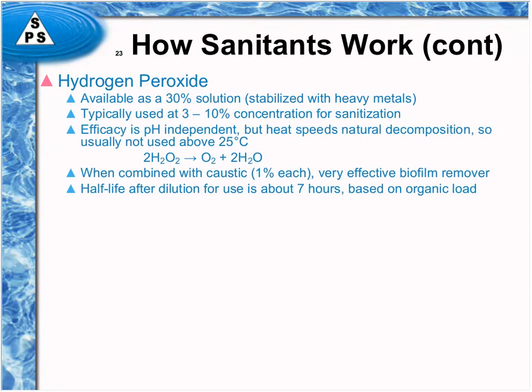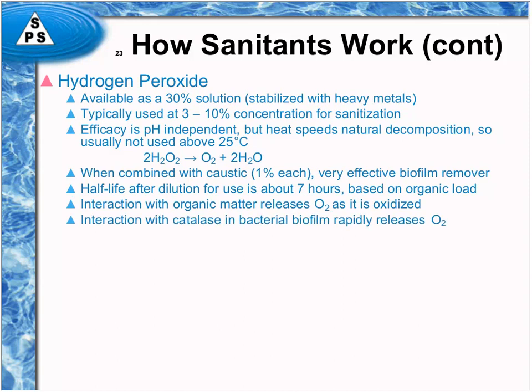7 hours or so, but that's highly dependent upon how much organic load you have in the water as to how long that is. It might be much shorter than that if you have high organic levels. The interaction with organic matter often releases oxygen, so make sure that you have your system able to be vented. Otherwise, it'll start to build up a lot of pressure.